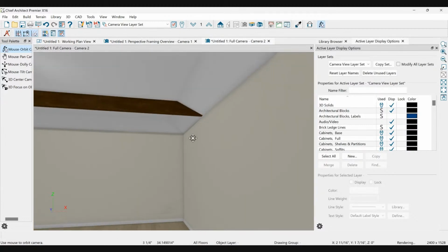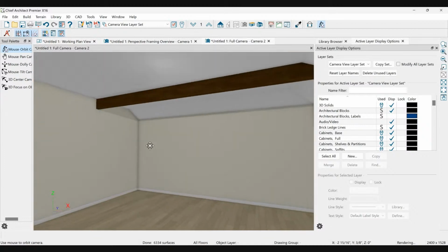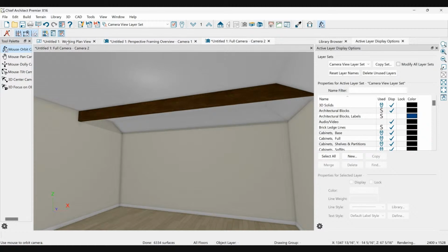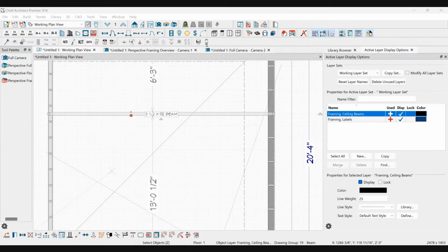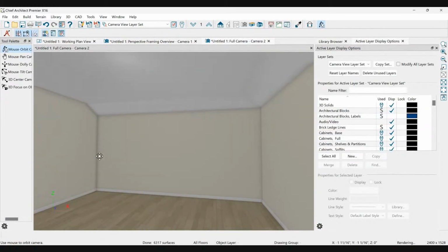So you do this. Now, this is all fine and dandy, but as you can see, we can't put the beam here anymore because it would stick out. Unless you wanted a cool feature where the beam sticks out, you have to pick the beam up. So, fine, we're going to transform replicate this beam up 12 inches and put it back above the ceiling. Now we picked the beam up above the ceiling, it's gone, everybody's happy.